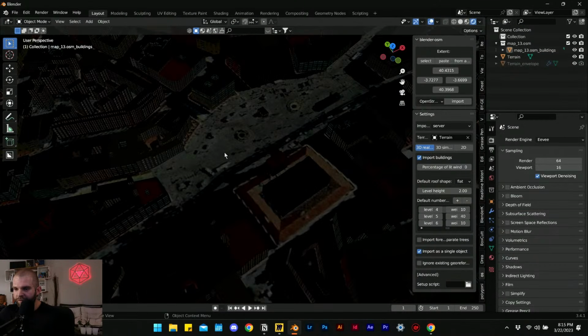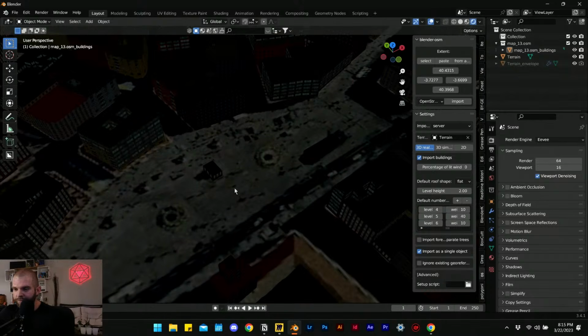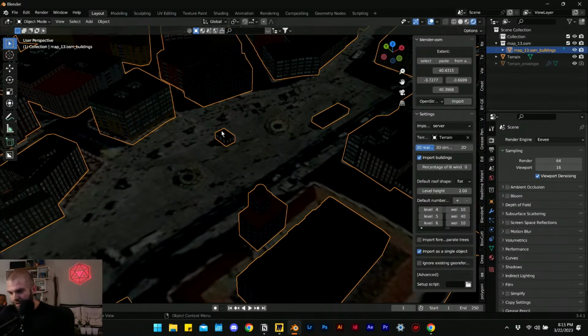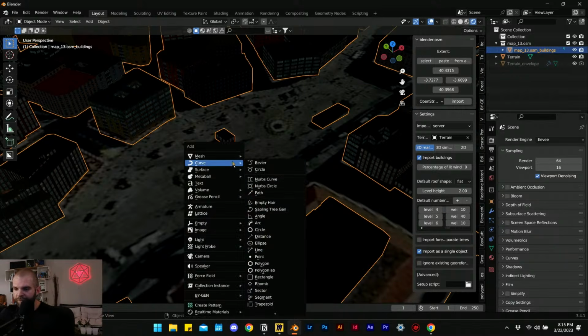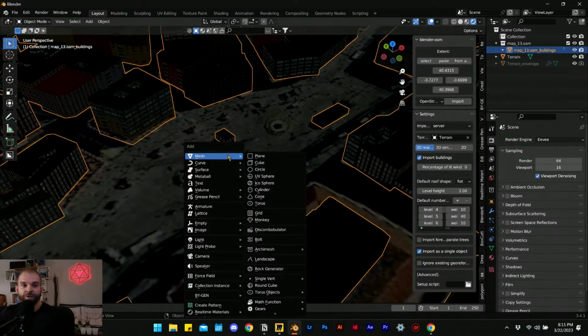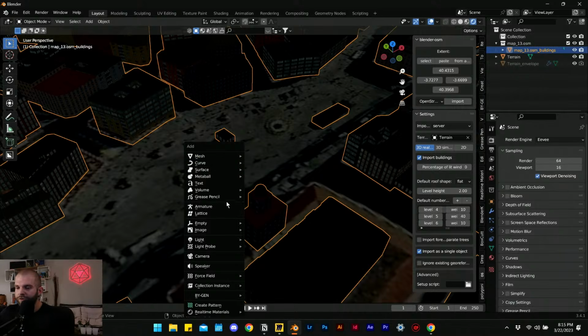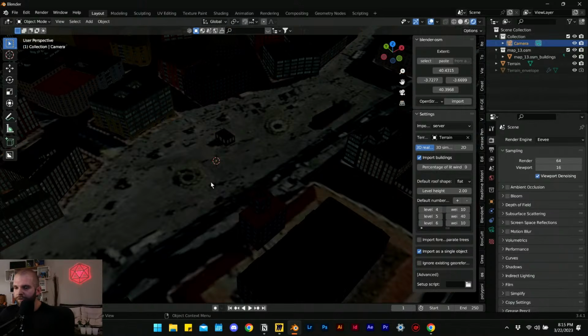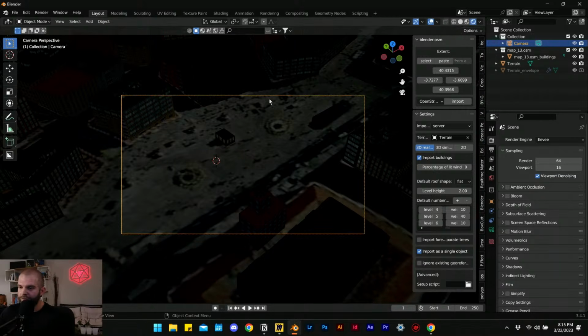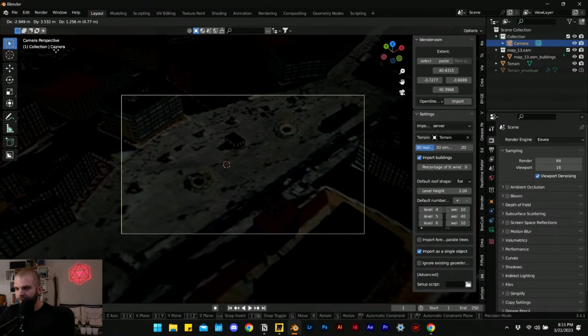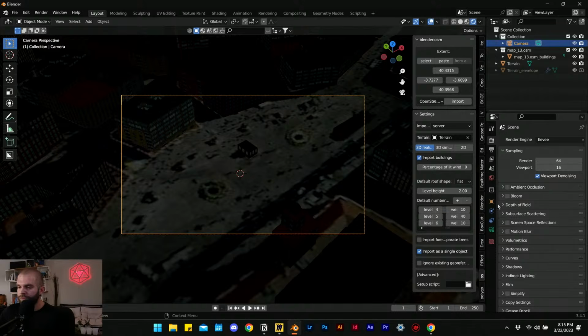So there's this plaza right here. It looks like Plaza Mayor, so let's run with that. We don't have a camera in this scene, so I'll hit Shift right click to make the center of the plaza the center of my model, in a sense, or at least have geometry come out of this area. I'll hit Shift A and add a camera. With the camera in the scene, I can hit Control Alt 0 to have the camera snap over this section right here. And what I'm going to do is go to Object Properties.